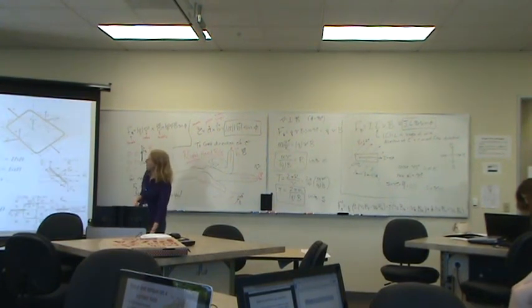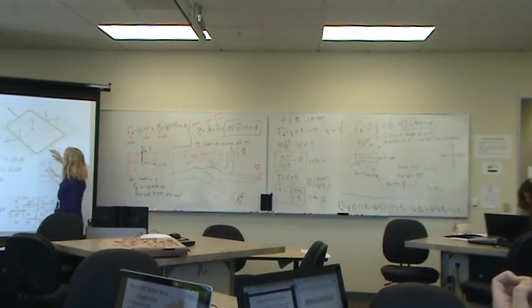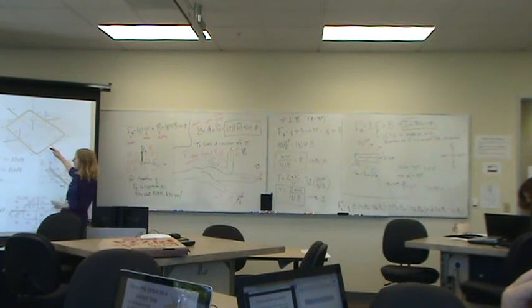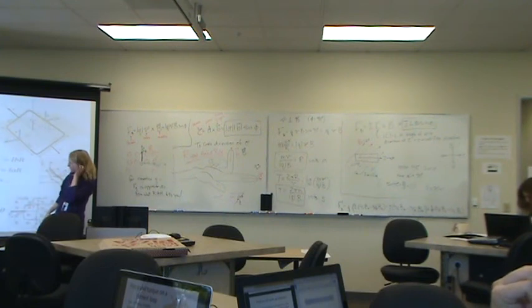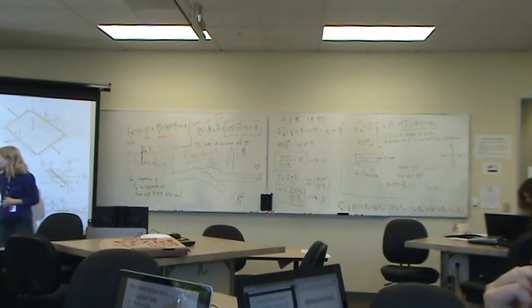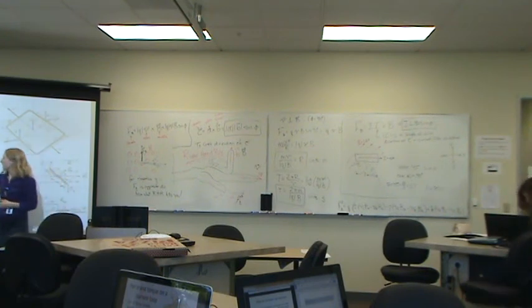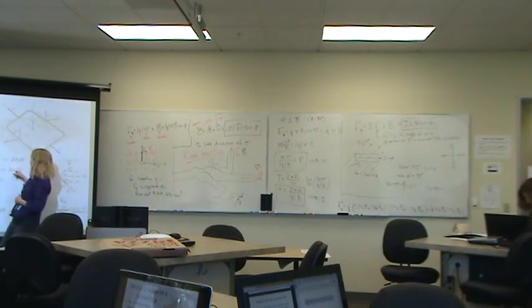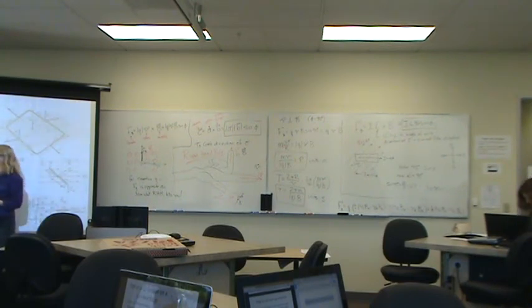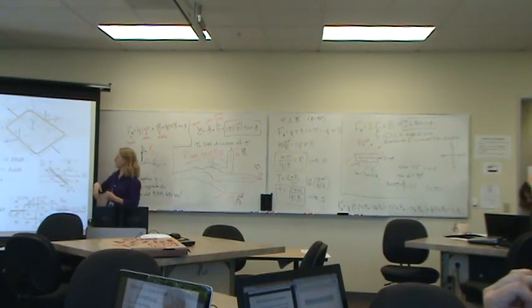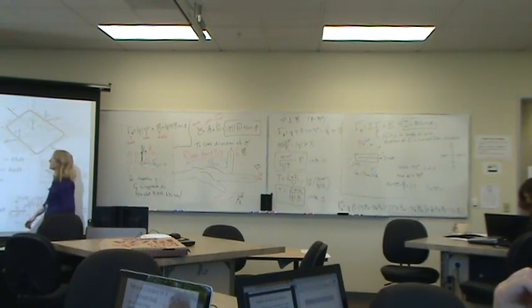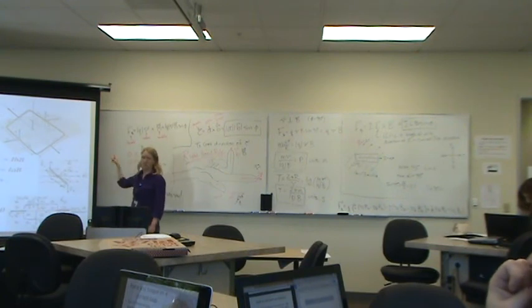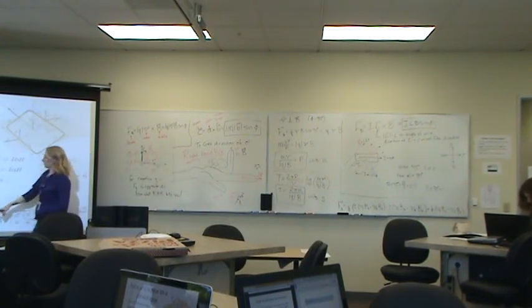And then the sum of the torques, we talked about how torques 2 and 4 would be 0 because the R values are 0. And these torques would be non-zero. So torques 2 and 4 is 0. So torques 1 and 3, the R value is B over 2. The force we calculated for force 1 and 3 was A big B. And then theta is going to change as the loop rotates. So we're going to keep it theta in the equation. The negative comes in because of the way I drew my picture. It's going clockwise when it's rotating. So that's why we have to have a negative on our torque value.